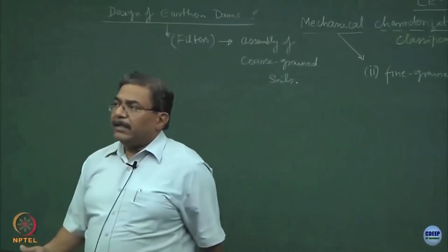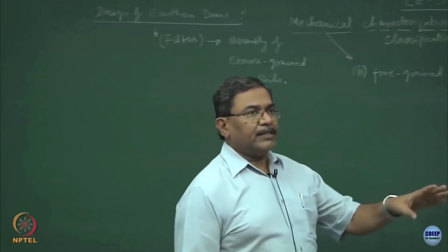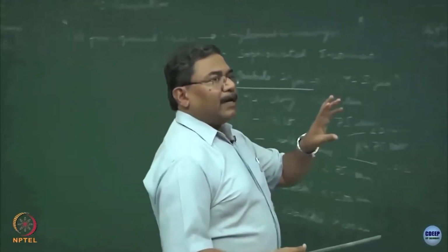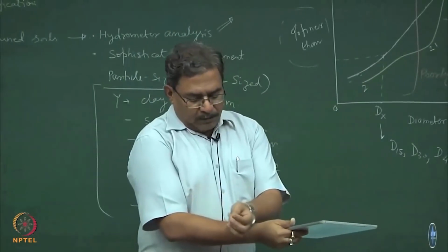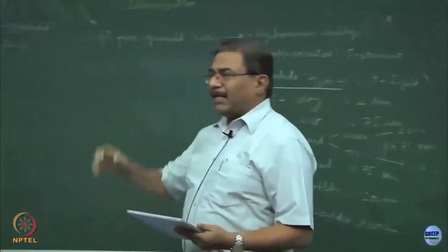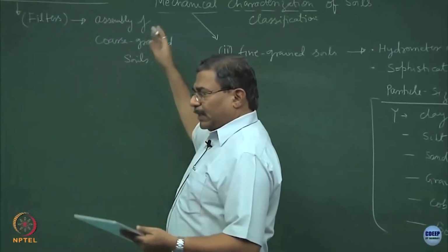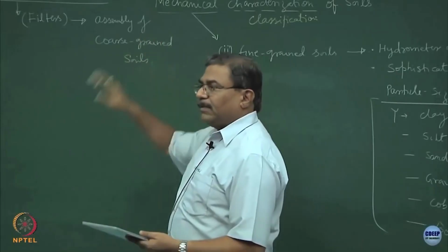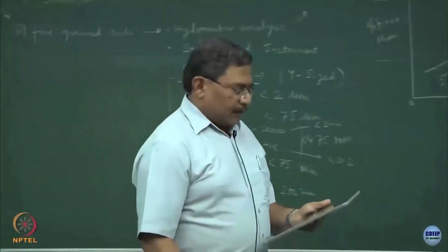Swimming pools normally have granular filter beds through which the water trickles, and these granular materials are quite prone to giving shelter to bacterial activity. They get converted into biofilters, through which I can pass the sewage, and the sewage can be treated. So, those of you who are interested, learn this more and more.